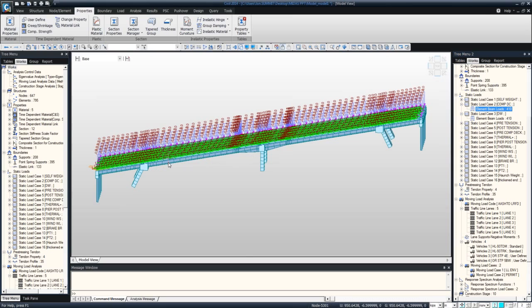And what I did was superimpose an assumed value of 3 inches, which should be a conservative value, and also assume that the increase in section depth didn't contribute to the effective composite section property. So that makes it conservative as well, because we assumed a slightly thicker haunch, and then also didn't allow that to increase the section property. I won't go through every load I imposed on here. It's pretty standard loads.